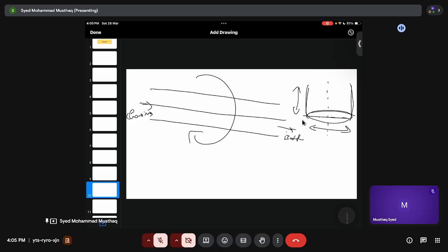Again, the next thing is the type of furnace and the type of coal, or the energy reducing agent, you are trying to use. If you use electricity, then it will be electrical smelting. If you are using a charge bed, then it is a bed type process. And if you are using a bath process, then it is a different metal slag bath. So that's the maximum difference. Again, the names will come like Technored, Corex, Finex, DOS, Cyclone. If you use a cyclone type of furnace, then what happens?